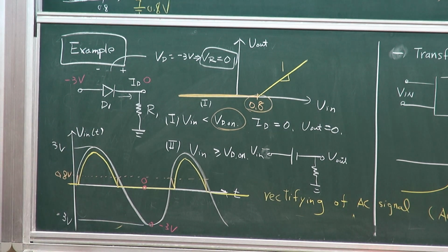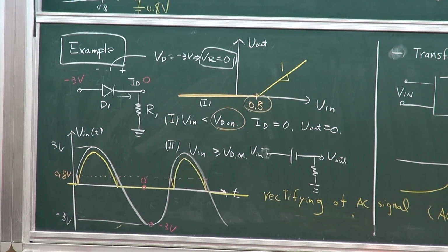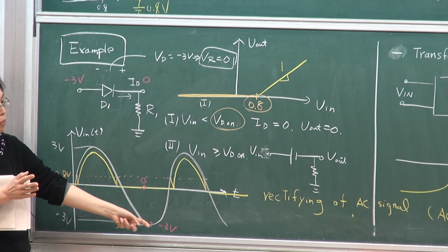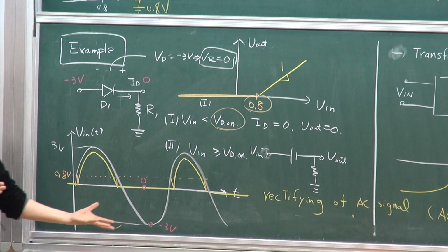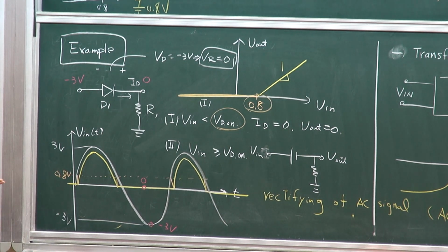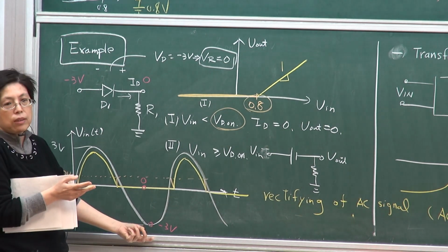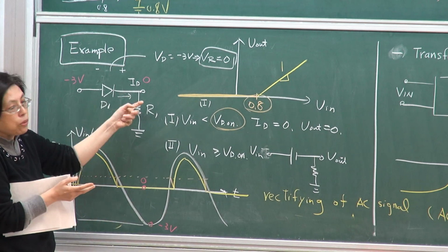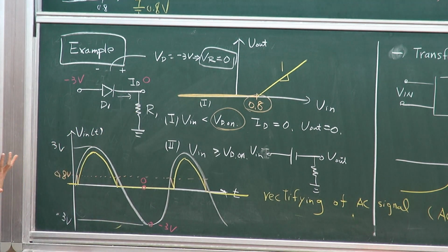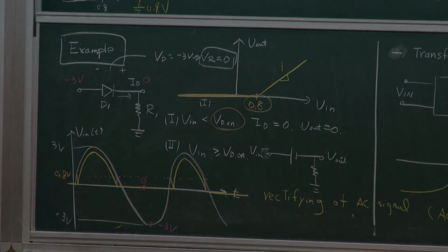So the main purpose of the diode is to sustain this voltage. When we talk about rectifying design, you want to make sure you pick a diode with high enough breakdown voltage, otherwise the circuit wouldn't work, it will break down. Let's say with a 10 volts breakdown voltage, you're applying 12 volts, it will then allow current to flow, even in the reverse direction. Okay?